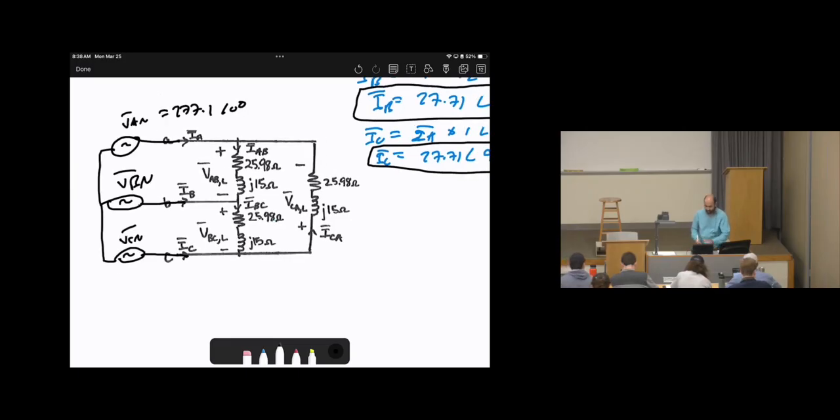Okay, the load is delta. It is a three-phase problem. So according to our procedure, let's convert three-phase to single-phase. Are we able to locate phase A, to say isolate phase A from the circuit? Someone can say, okay, this is phase A. Okay, where should I go? This way, this way.